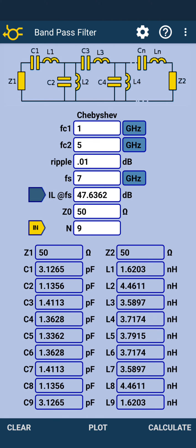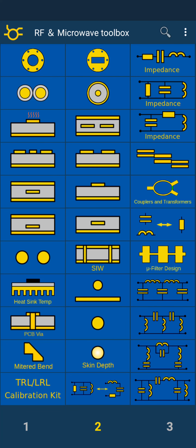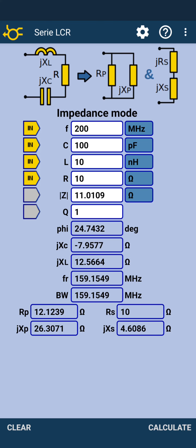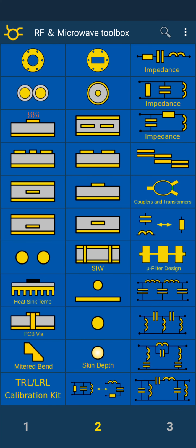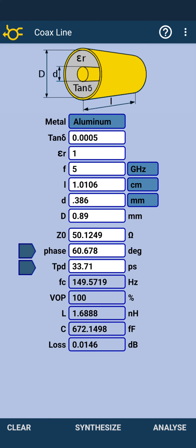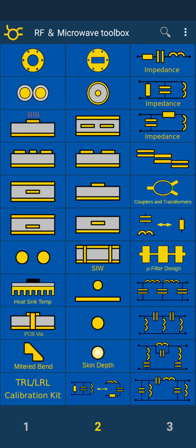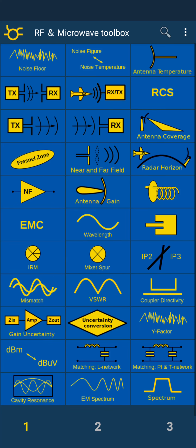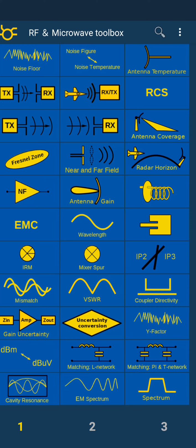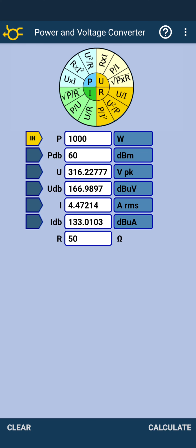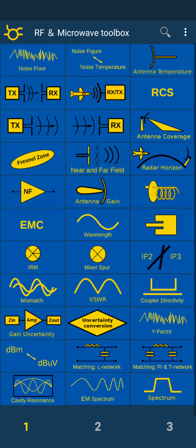And then once you've got your design, even then it's not just, okay, I've connected these things together. You've got to be able to really fine tune it, make sure that it's performing optimally, and they've got all these converters built in. That's right, like power and voltage conversions, noise temperature. You've got VSWR, return loss, all these critical parameters you need to be aware of. It's almost like tuning a musical instrument where you have to adjust each thing just right to get the desired sound. Exactly, that's a great analogy.